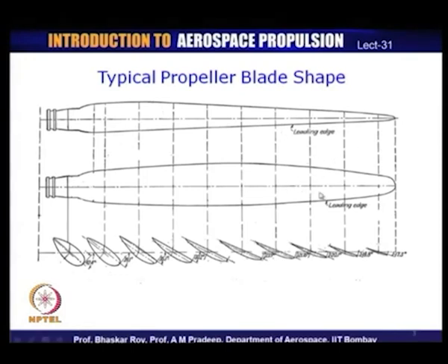If we look at the propeller blade, this is the leading edge. If you turn the propeller, this is also called the leading edge, which, as you will see, is a comparatively flatter surface. So, if you look at this propeller blade, this is, let us say, the top surface, which as you can see has a curvature, whereas the bottom surface is the surface we call the leading surface, that is, the surface that moves forward in rotation.